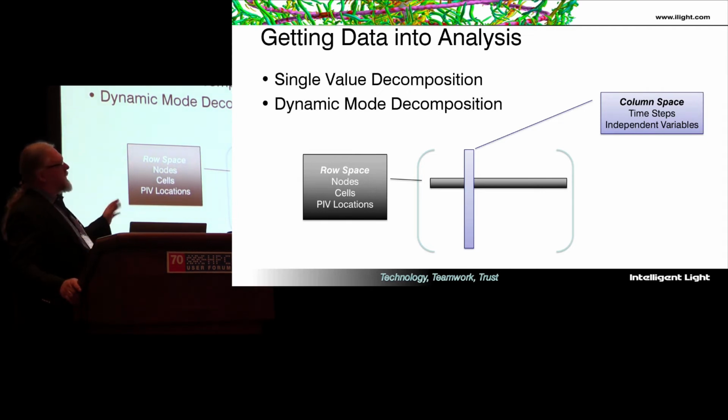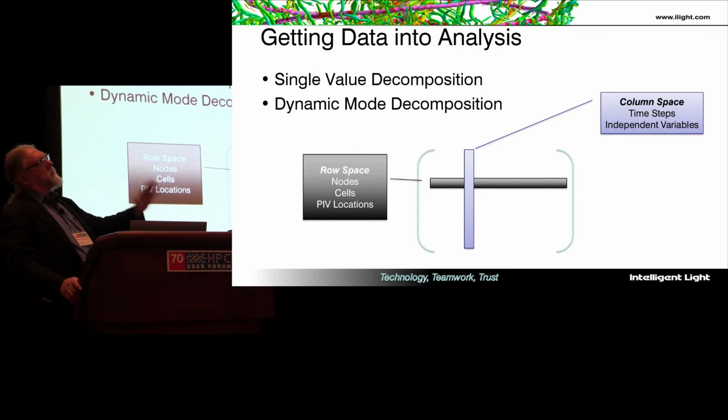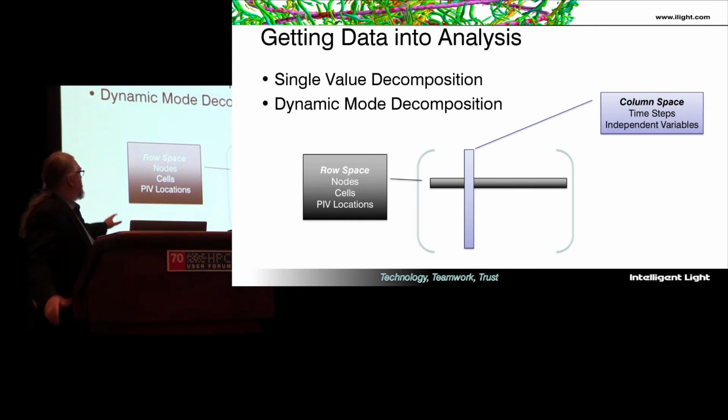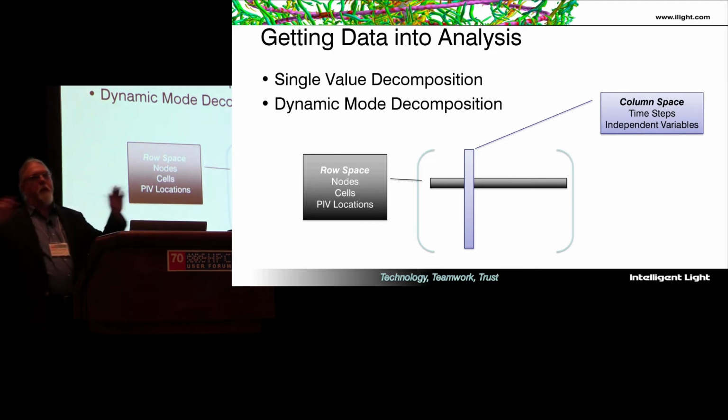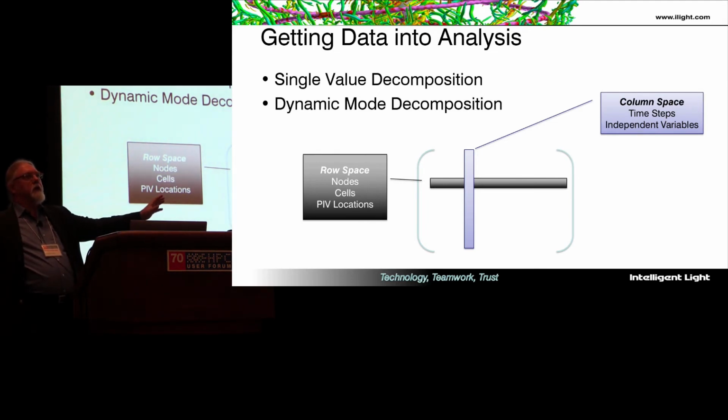Just like in machine learning, you do simplification such as convolution up front, or eigenvalue analysis up front, in order to simplify things going into the neural network. There are many types of tricks and techniques to use here. For example, if you're doing proper orthogonal decomposition, you can do it separately on each of the parallel domains and then combine them together using an iterative technique called hierarchical POD.